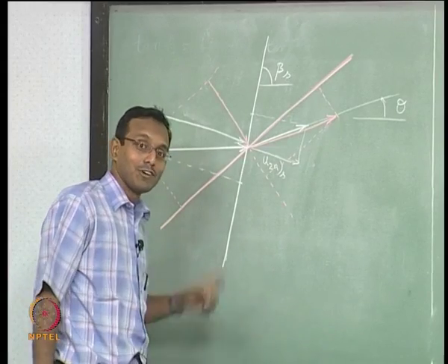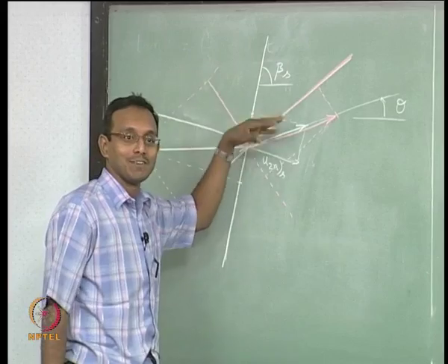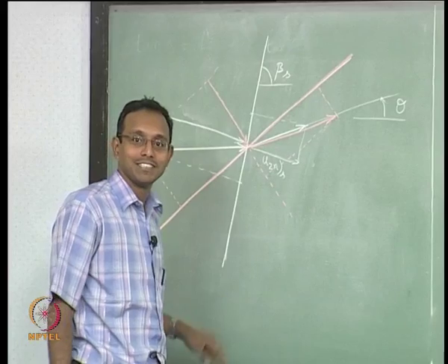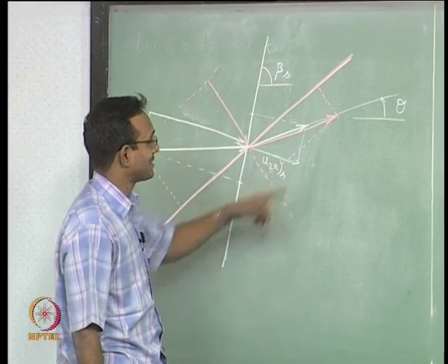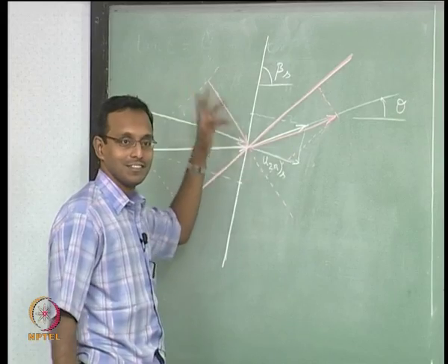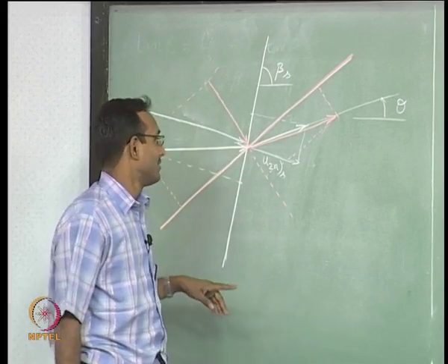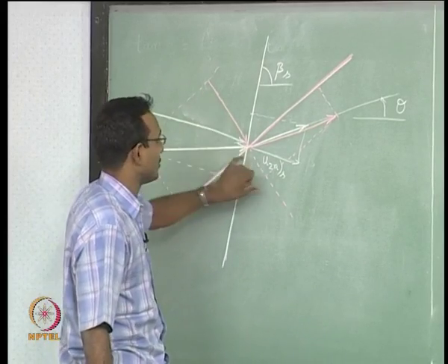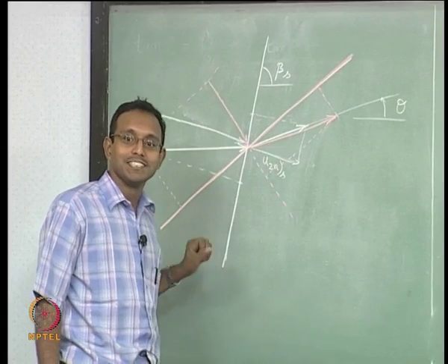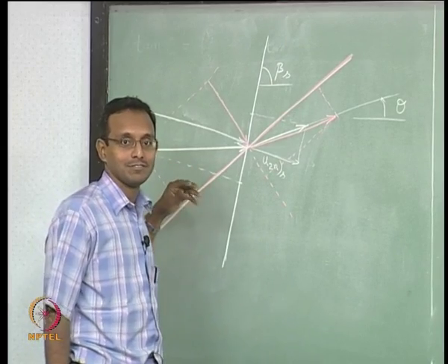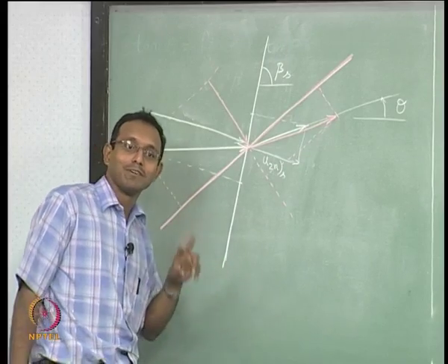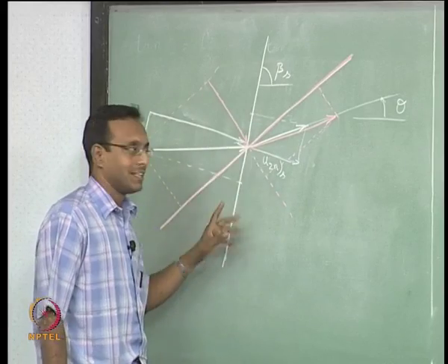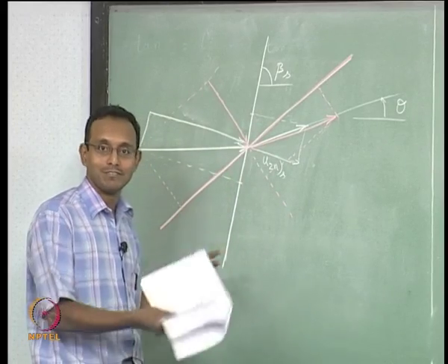Now, you may ask, if I follow the same procedure, I can draw how many ever shock angles I want with the same angle finally. If I already fixed the theta and choose beta and draw all this, I can do that. But you should know that I do not have the freedom of choosing u1 normal to u2 normal ratio. That is decided by normal shock relations. Okay. It so happens that the relations will permit only two such values, not any angle you choose. That is what your equations are showing, that is what your final plot is showing.